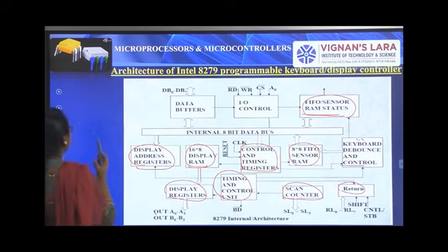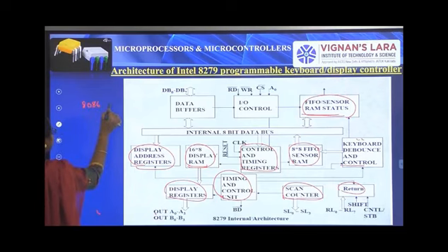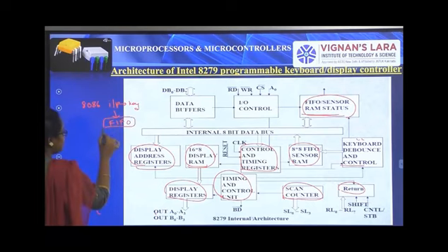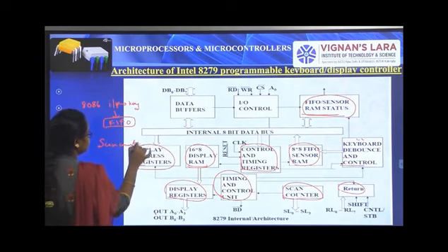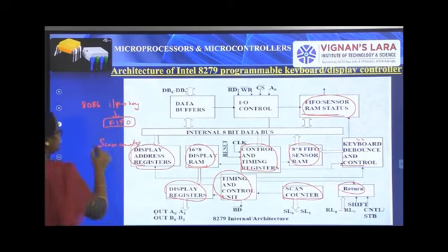So whenever we give input from the keyboard, which is present in the FIFO RAM, that input is scanned by the scan counter, and it is given to the 8086 microprocessor by using the interrupt request command.